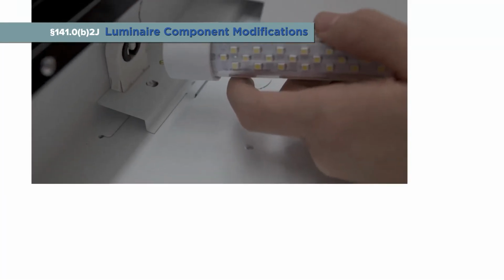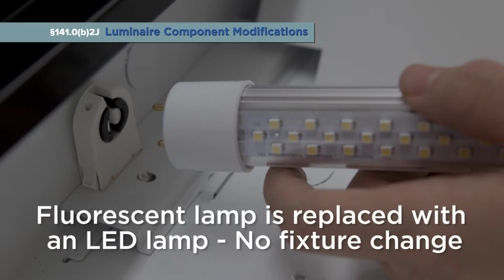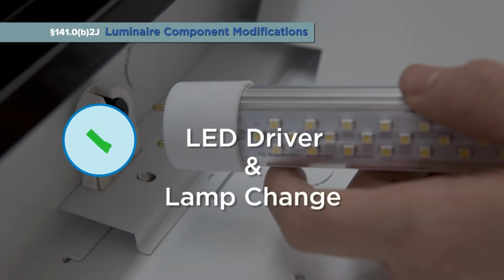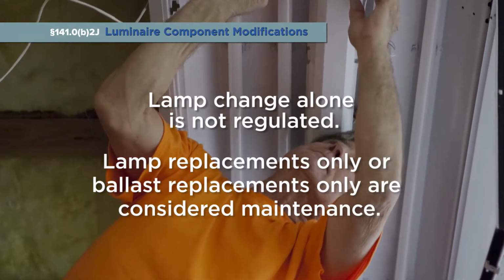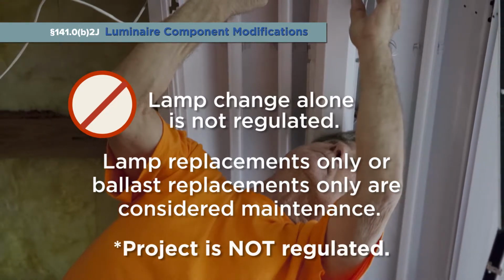Let's go back to our example project where a fluorescent lamp was replaced with an LED linear alternative, but the troffer did not change. If the project also requires that the fluorescent ballast be replaced with an LED driver along with the lamp change, it is considered a luminaire component modification under Section 141.0B2J, since we are replacing both the lamps and the ballast with new components. If the project only replaced fluorescent lamps with LED lamps and the fluorescent ballast was left in place as part of the functioning LED system, then this is not a regulated project.